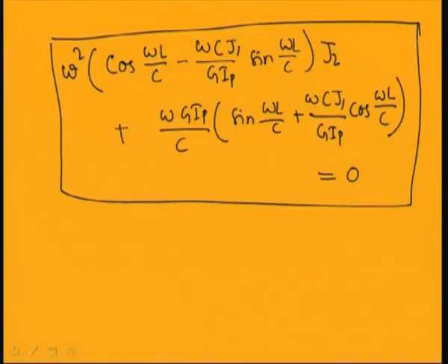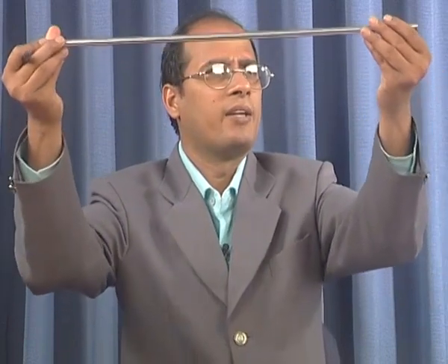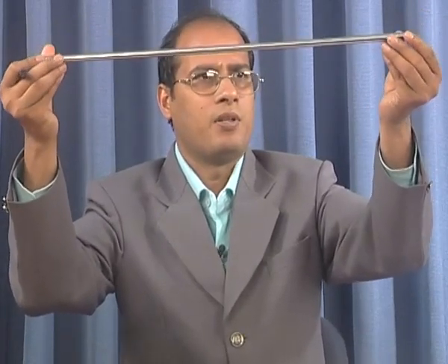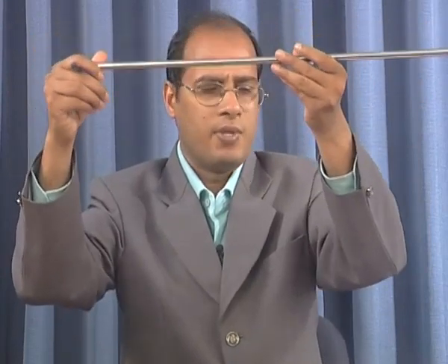This is the rigid body motion in this case. So, when omega equal to 0, the system will have a rigid body motion. In this case of torsional vibration, the whole system will freely rotate and you will have omega equal to 0.